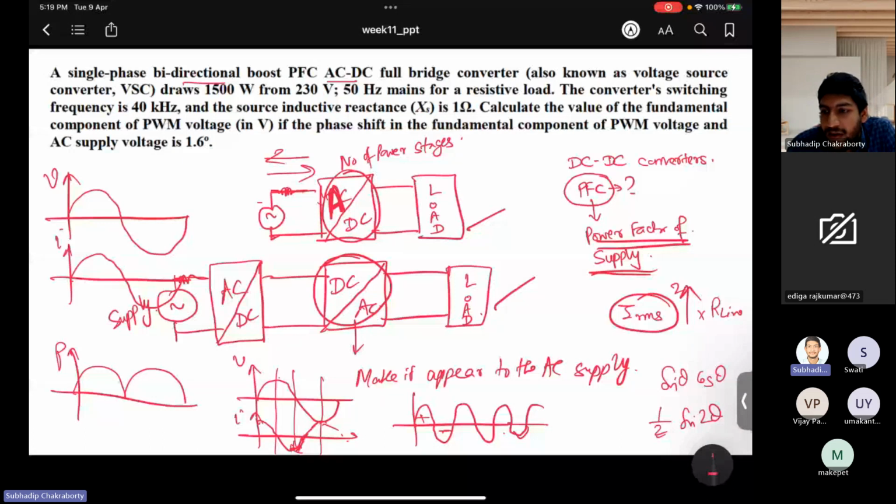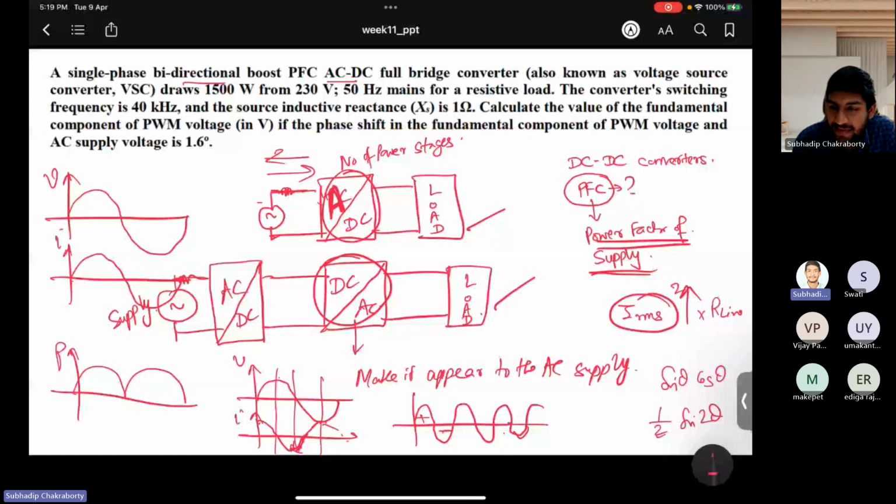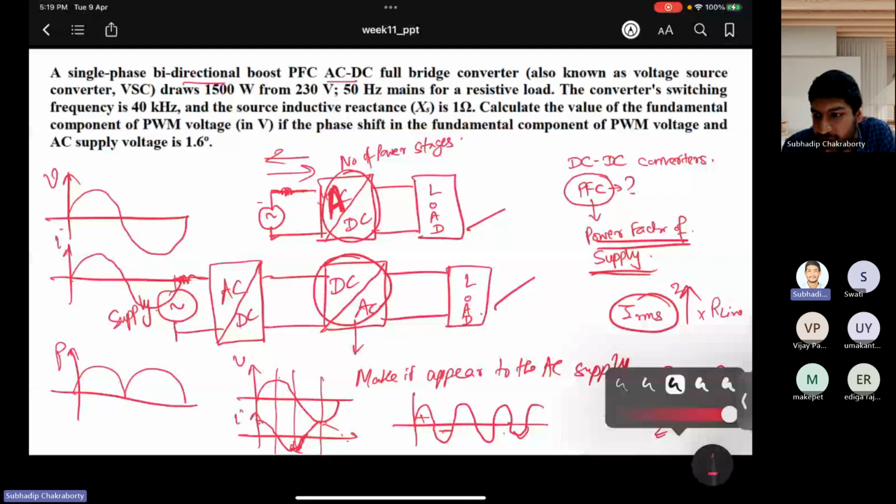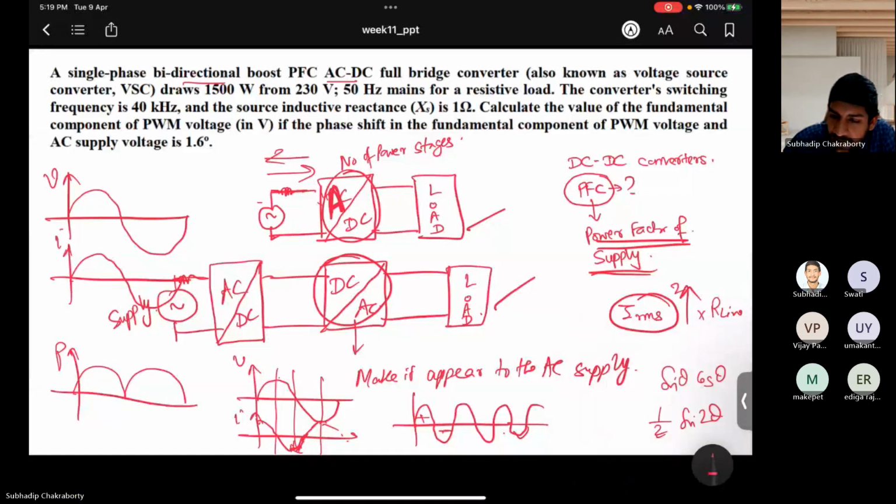So that's why a limit on the power factor, on the usage levels of the consumers, is imposed, and a two-part tariff or even a three-part tariff is introduced. You must have seen, to penalize the customers for exceeding their maximum reactive demand levels. If they exceed those demand levels of reactive power, they are penalized in the current tariff structure. So that's why we want PFC for your devices as well, like for EV charging applications, and also for feeding some loads or charging some batteries. For e-rickshaws also, some chargers are there.